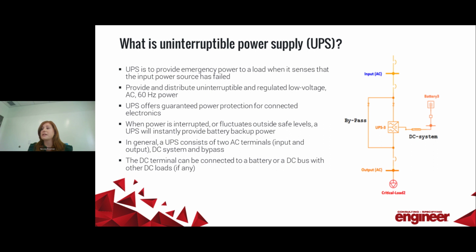There are also other accessories that can be purchased with a UPS system, including a rectifier to convert your AC input to DC that would then go through your inverter, a bypass switch, which will bypass the inverter to an alternate AC supply in case you need to do maintenance on your inverter, and a static switch, which transfers the UPS from the inverter to a reserve supply in case of total inverter failure.